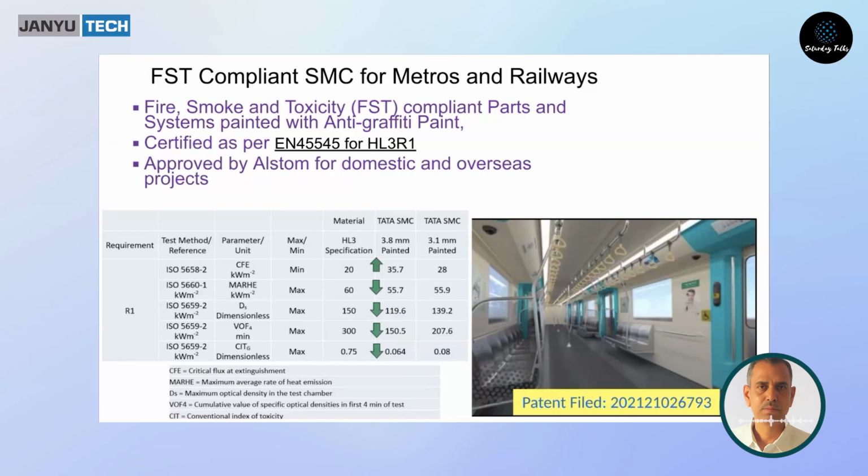Yeah. So there is a 3,000 ton press. I think, sir, when you were there, they got this press. Probably you did not visit. Yeah, I remember. I've seen this. You have seen this, sir. And it also has parallelism control. It controls the part planarity at 20 to 24 micron level.